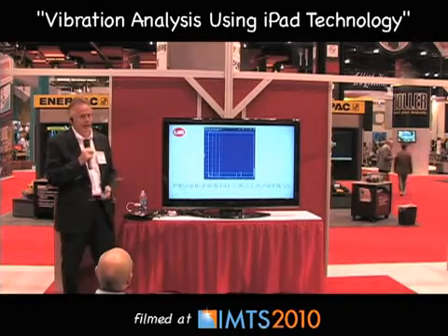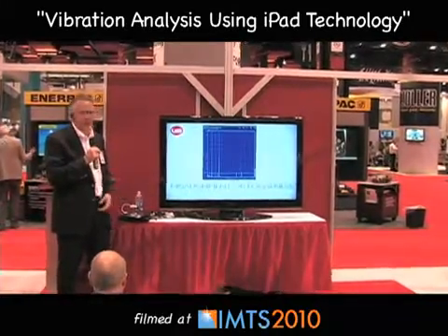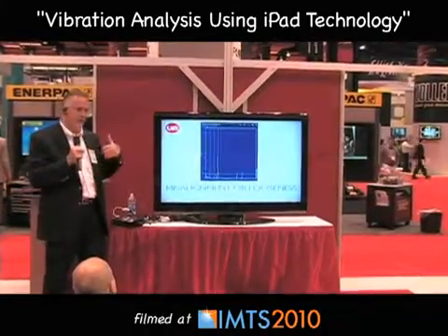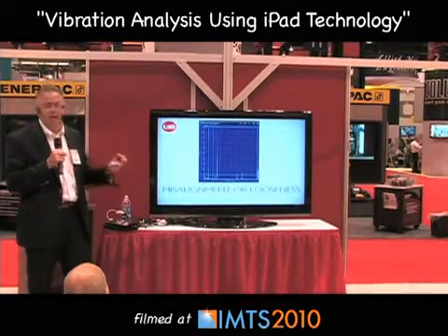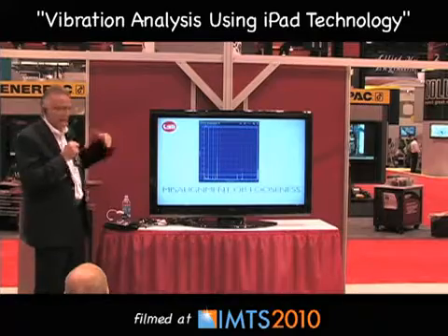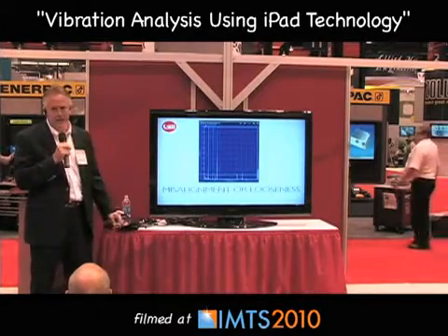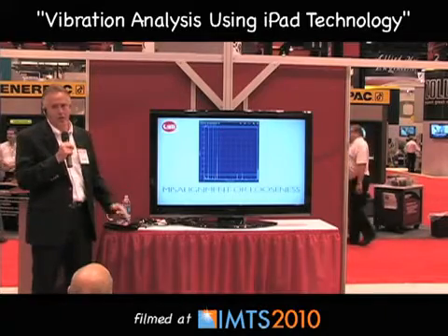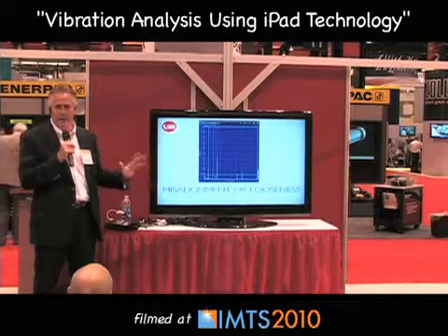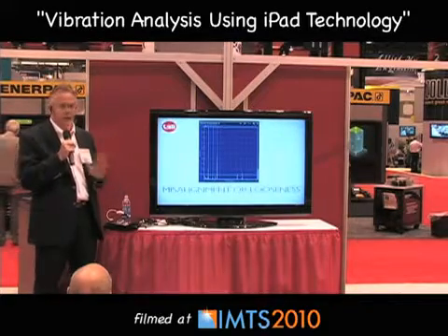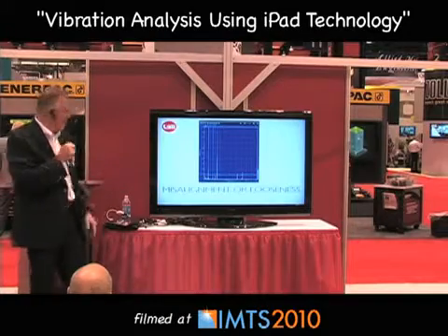The other thing to look at is, a lot of times something might be vibrating and it might be a simple issue. Very often somebody could put an imbalanced pulley or an imbalanced tool on a component, and it will damage the bearings over time. But with the vibration analyzer and throughout your route, you'll be able to pick up on these things, and you'll be able to know by looking at the signature that, all right, I don't have a bearing frequency issue here, I don't have a bearing problem, we don't have to prepare for failure, we just need to put a balanced tool in this and then we'll be operating properly.